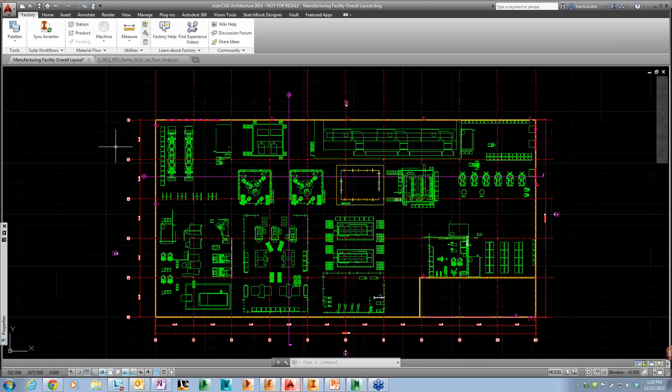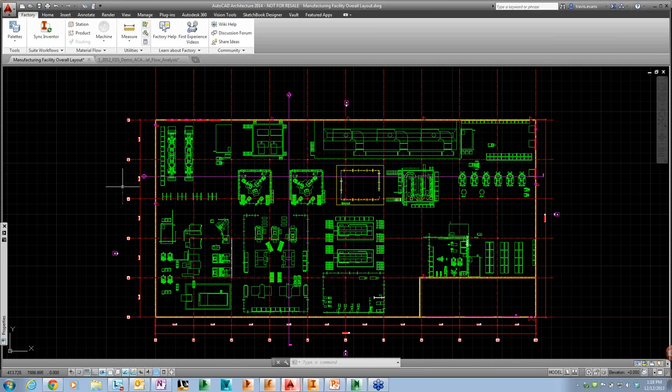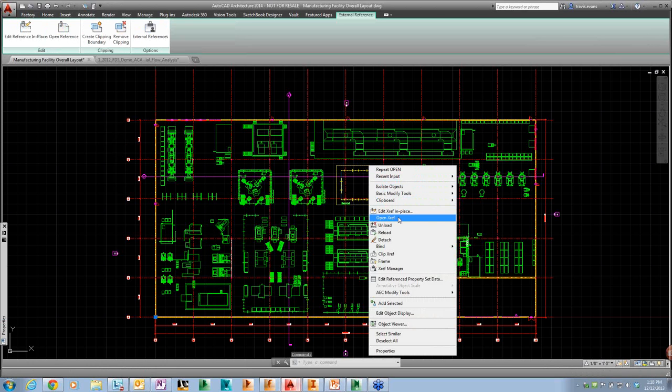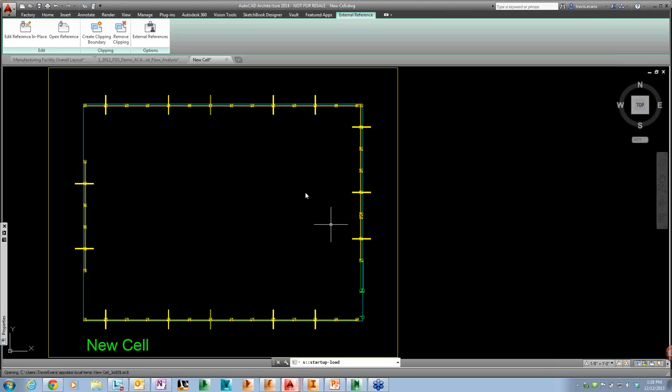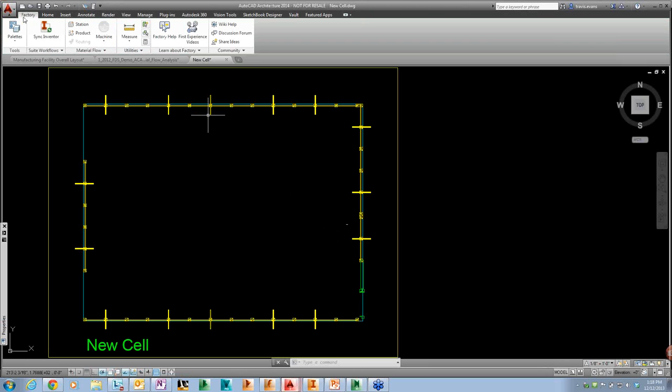So, I mean, the majority of our customers are using AutoCAD, and probably the majority of them are using something like an XREF. So if I'm talking about a huge facility and I'm wanting to make a change to one simple work cell, one simple location, probably doing it with XREF. So what I can do is leverage those XREFs and make them a little bit smarter. So I can add a little bit more functionality to those as they start to connect into that 3D environment.